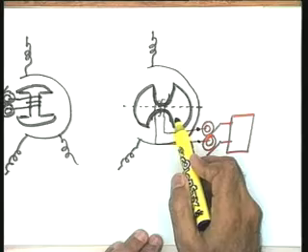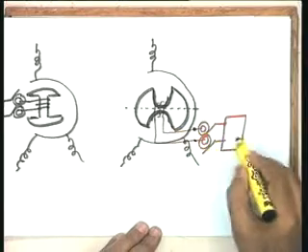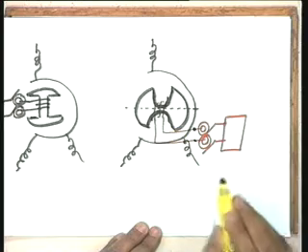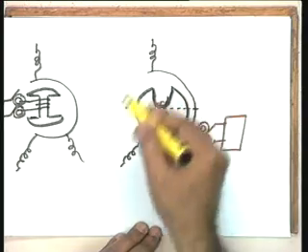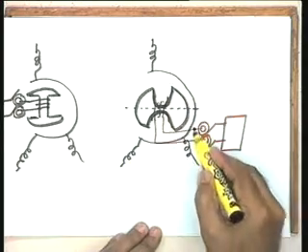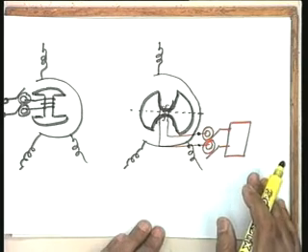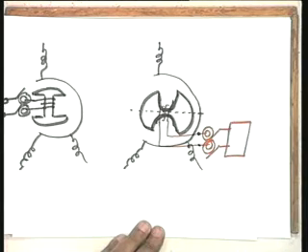If the rotor is not cylindrical, then the impedance as seen by the signal conditioning device will become a function of the rotor position. So I have made it more or less cylindrical, so that the impedance as seen by the signal conditioning device is not a function of the rotor position.